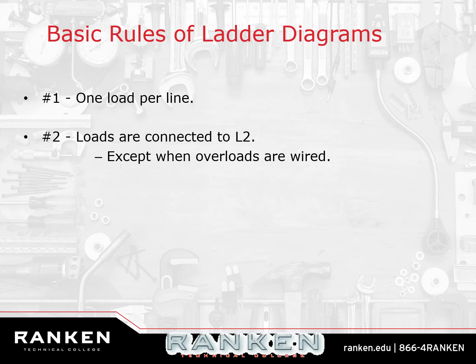All loads are connected to L2, an unbroken chain to the ground or to the neutral or to negative, with one exception. The one exception is overload relays for motor starters. Because we want to be able to definitively kill it when we have a motor overload.